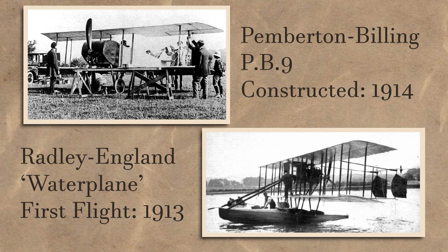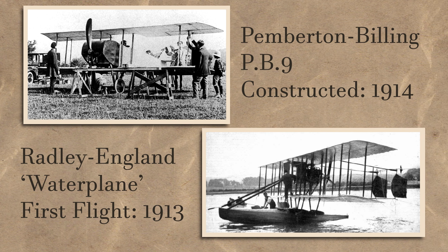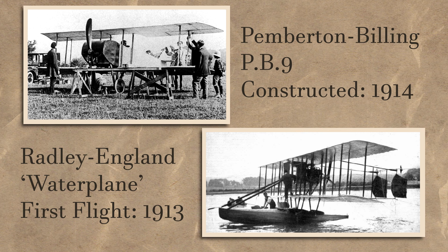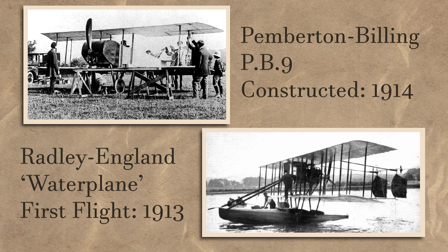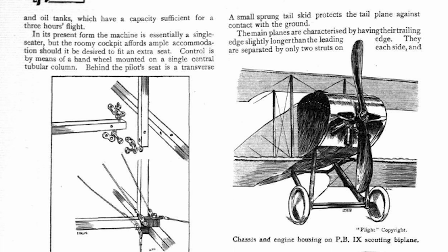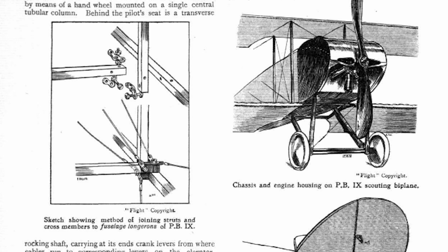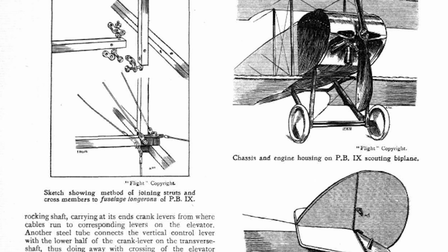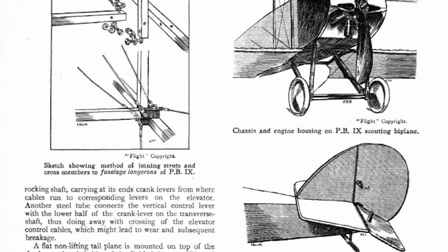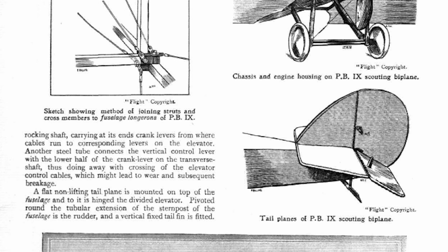These were simple one-piece designs, and it took little effort to design a straightforward fuselage to go with them. In fact, the fuselage merely rested on the bottom wing and was attached by a handful of U-bolts. Hoping for a large production order, Pemberton-Billing designed the fuselage to be built from methods found in any joinery or cabinetry shop in the country. The main structure was built using mortise and tenon joints, and complexity was kept to an absolute minimum.